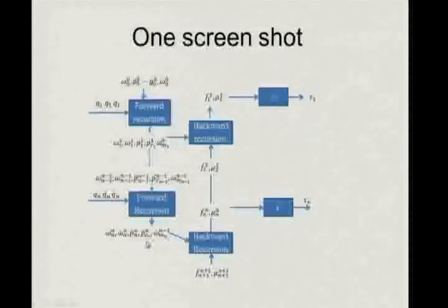So if you want to look at this overall summary, you define what is happening in the base, and then you define the velocities and accelerations at the joints. Then you do forward recursion using q1, q1 dot and q1 double dot, and then q2, q2 dot, q2 double dot, all the way to qn, qn dot, qn double dot.